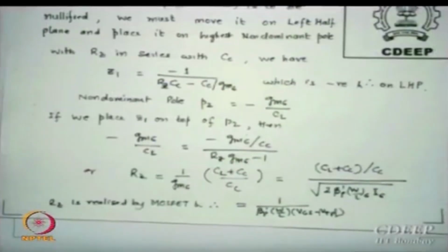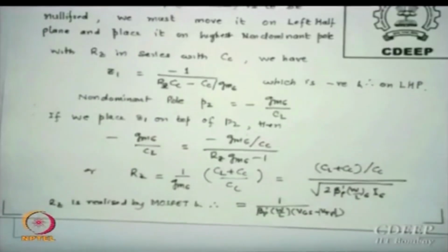And then your bandwidth essentially is not directly hurt by this method. So to improve your bandwidth, one way is to null the non-dominant pole and keep CC lower. Is that clear? So this method of nulling is very powerful. The only problem is, what is the only problem you get? All these values are varying with all kinds of variations. So getting this relationship exactly, that they null, is not very easy. So some pole will still occur, but by magnitude it will be so small that it will not interfere with P1 in any sense. That is the trick of that.